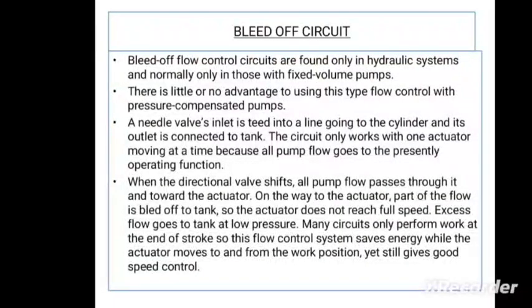Next we'll move on to the third circuit. So the first circuit is metering in, the second one is metering out, and the third one is the bleed off circuit. The bleed off control circuits are found only in hydraulic systems and are normally only in those with fixed volume pumps.